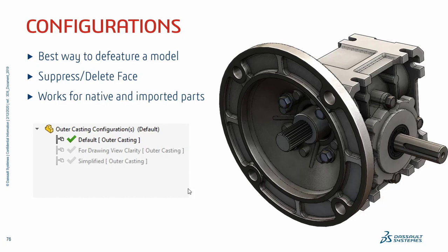In the assembly we don't need that extra detailing, we just need the representation of it. So please use a configuration for the simplified version, and add that configuration at the assembly level. It will just represent the component there, since that much detail is not needed.